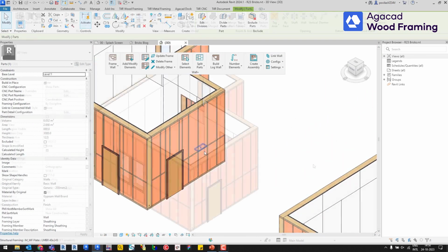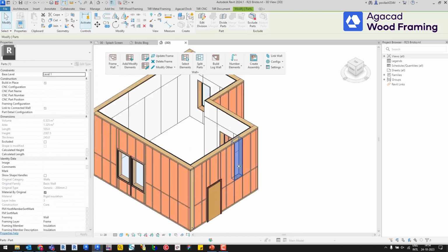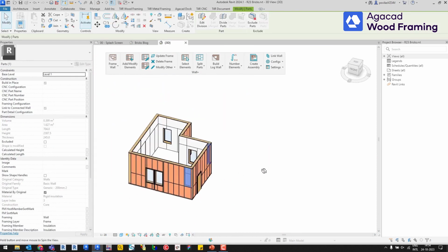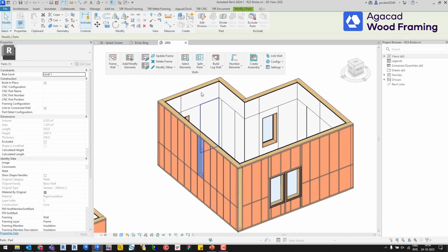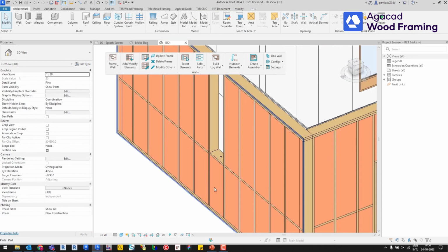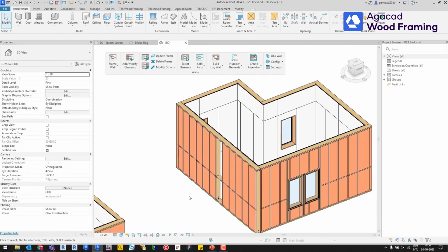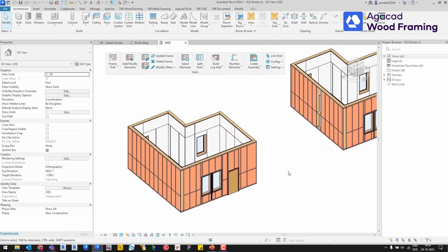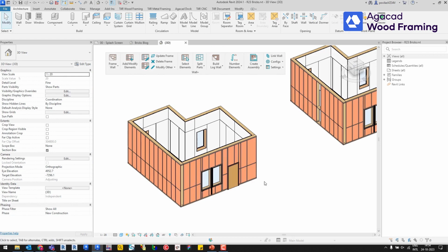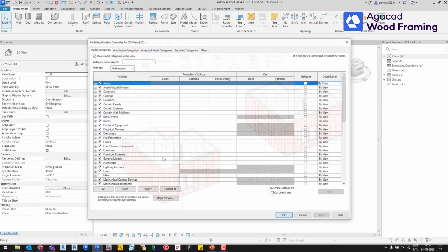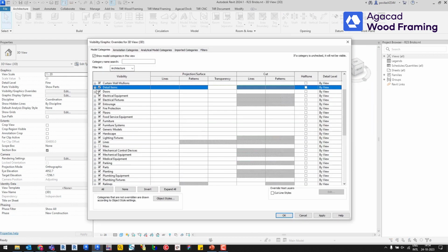So for the bricks, as with everything here, you have to designate a particular layer in the wall. The outermost layer will be your bricks, so you'll have to dedicate that layer and designate the depth of that layer, obviously. So the bricks can automatically adapt to the depth of the layer. You don't have to change the type parameter for the bricks in terms of the depth of the brick.